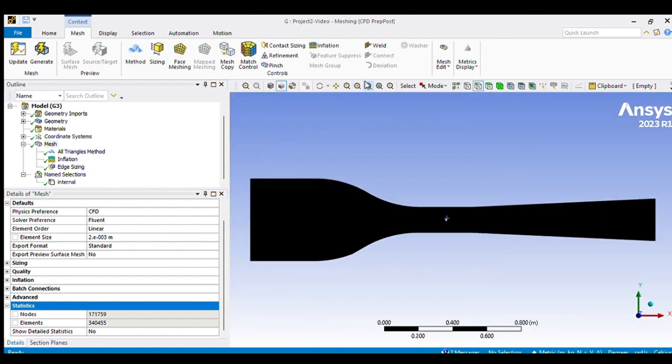Okay, now selecting boundaries of the wind tunnel itself, the velocity inlet, press N, name it velocity inlet. And the exit of the wind tunnel will be called the pressure outlet. So that's what it's named. Now defining the walls.